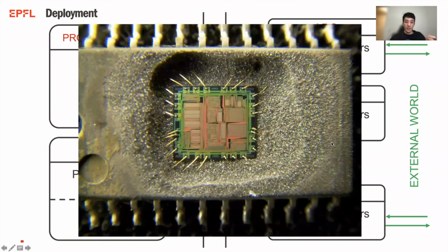Now, here are the internals of an MCU. For example, this could very well be the PWM block responsible for generating that signal, the input signal to be applied to the plant. And the PWM block has a pad where there's a wire connecting it to really one of the pins of this integrated circuit. So that's how the code you write can influence the external world.